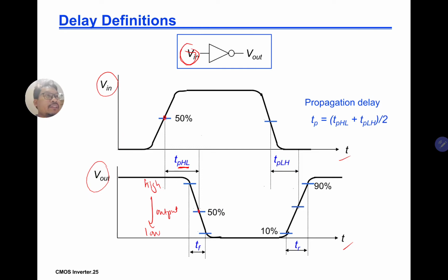And then we also have the definition of the fall time. The fall time, also, we are looking at the output waveform. So the fall time is looking at the 90% of VDD and 10% of VDD. Between that is your fall time, and of course you have your rise time, and then you have the TPLH. Okay, low to high on the output. Okay, not on the input. And of course you can have the average delay, or the effective propagation delay of the logic gate, which is just the average of the high to low and low to high.